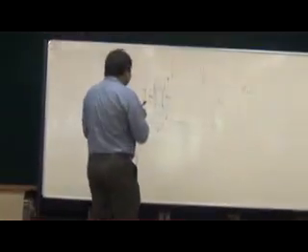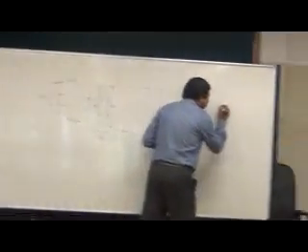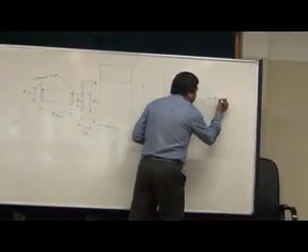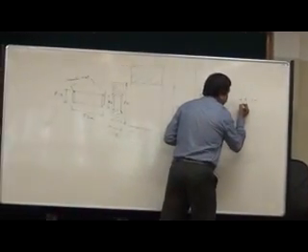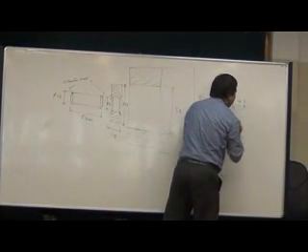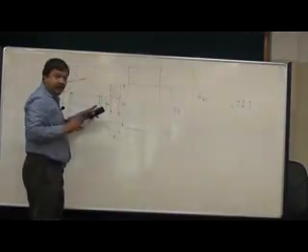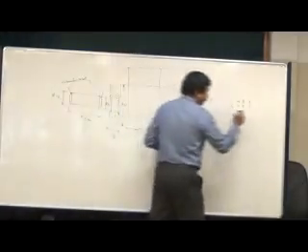So here the 16 mm diameter, the shaft 16 mm, make it as 16 plus 0.00 minus 0.01.